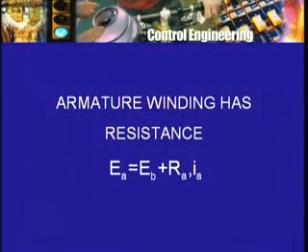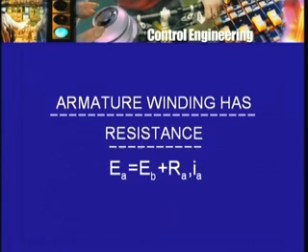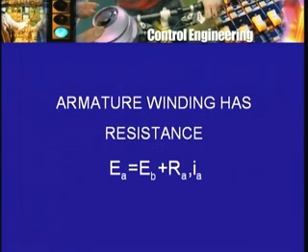There is this applied voltage, and of course, assuming that the motor is somehow rotating, there is the back EMF produced in the armature, and these two would be equal and opposite in their directions, but for the fact that in general there will be a current flowing in the armature, and the armature winding is a long electrical wire and therefore has resistance, and therefore